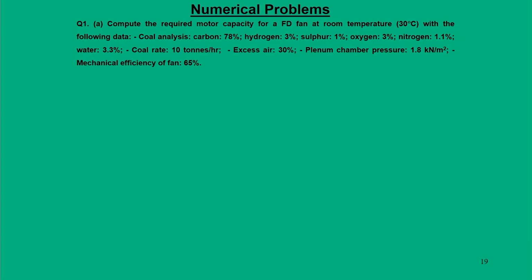one of the auxiliary components of steam power systems, that is fans. So, there are two types of fan, one is the forced draft fan, the other is the induced draft fan. The main distinction of these two fans is that forced draft fans normally handle only air because they supply the air requirement for combustion, and induced draft fans are used to take the combustion products out of the plant.